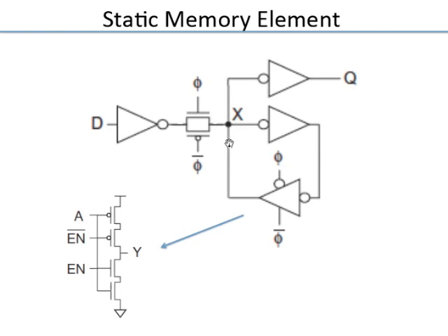Now this is the latch, right? This is the sequencing element, which is the latch. And really the key here as far as storing information goes is this loop out here. You see there are two inverters. Of course, this is a funny inverter. It has these additional inputs phi and phi bar, which is essentially a tri-statable inverter.